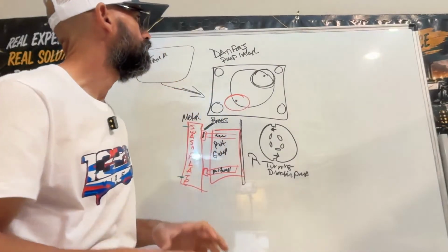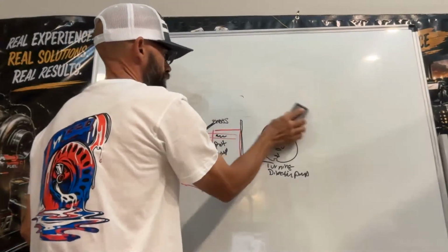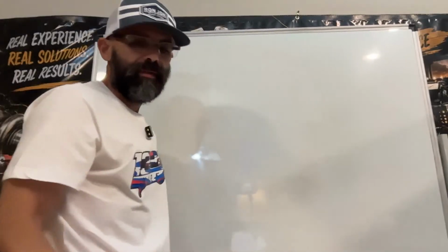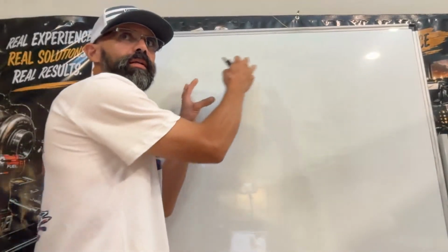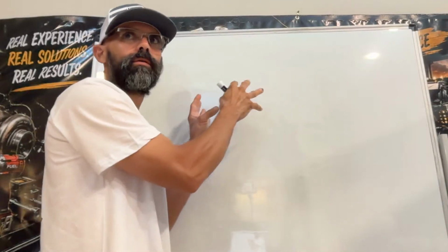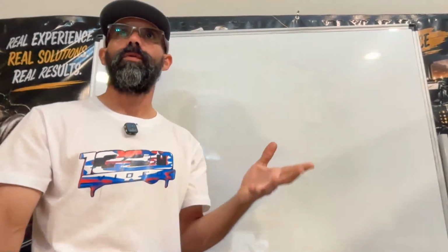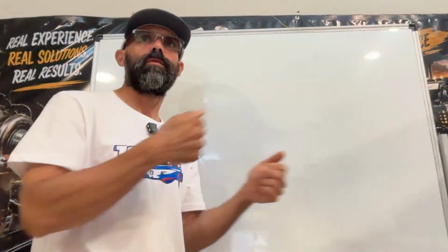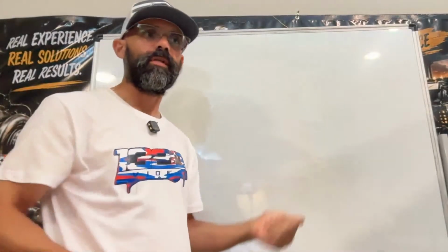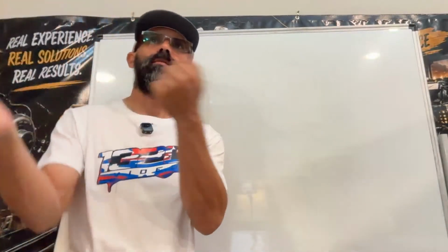So why does the pump need charge pressure? The pump needs charge pressure to replenish what is being lost as the system is running. Like the example I gave, closed loop, you had two guys passing back and forth a bucket full of oil. In the process, some of the oil gets spilled. There's a third person on the bottom catching the oil that gets spilled, then replenishes. That's charge pressure.